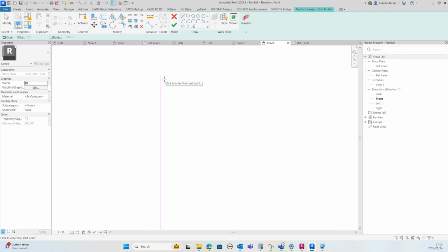So I'm gonna compose a railing. I'm gonna draw two elements at 20 millimeter thickness. So I'm gonna take it to the right like this, and then down at 90, I think. Let me make it 80 millimeters, and then I'm gonna take it to the left like this. So I'm gonna leave a spacing of 20 millimeters.